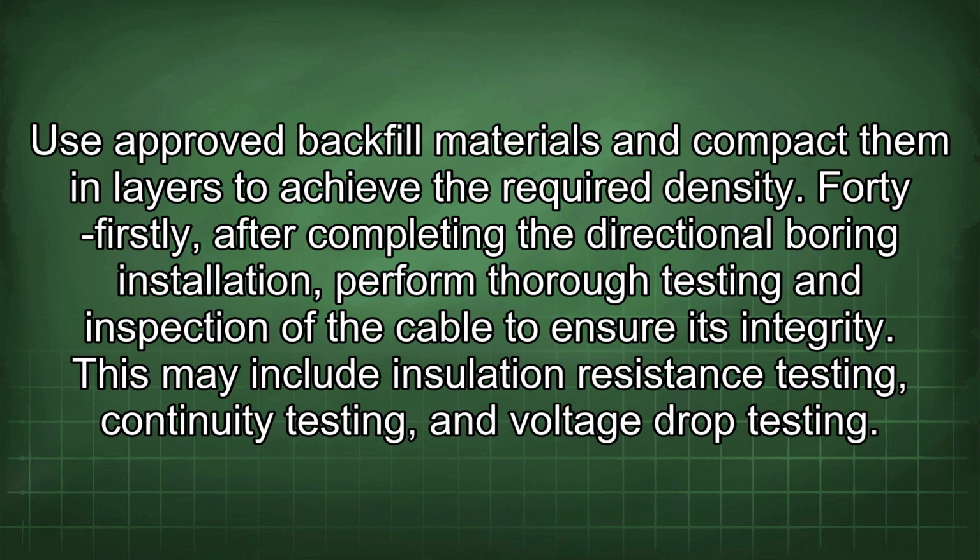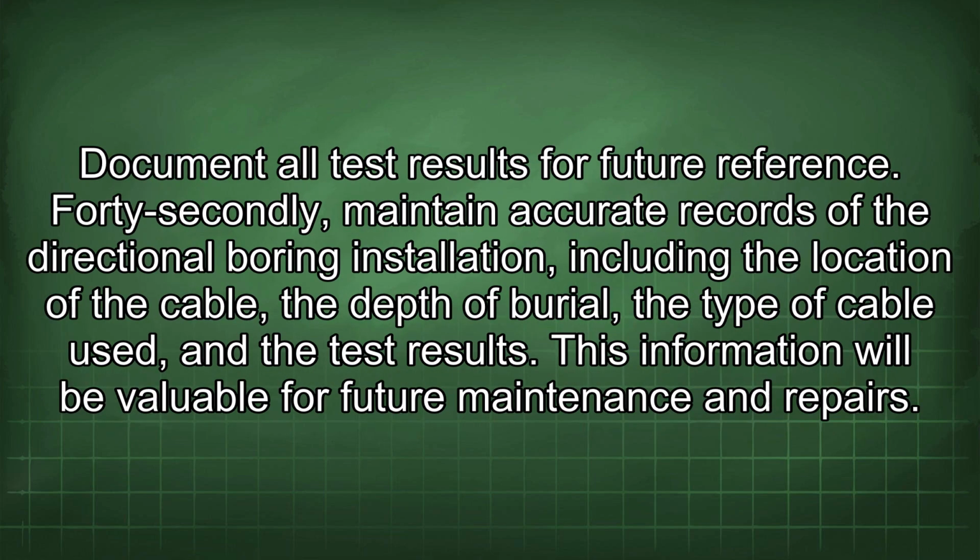41stly, after completing the directional boring installation, perform thorough testing and inspection of the cable to ensure its integrity. This may include insulation resistance testing, continuity testing, and voltage drop testing. Document all test results for future reference. 42ndly, maintain accurate records of the directional boring installation, including the location of the cable, the depth of burial, the type of cable used, and the test results. This information will be valuable for future maintenance and repairs.